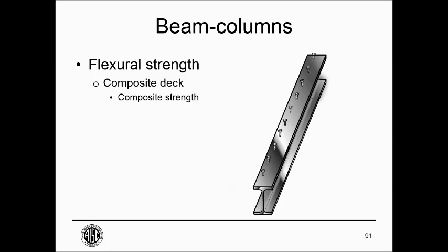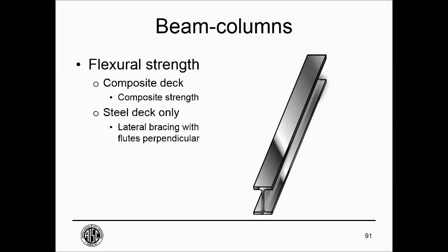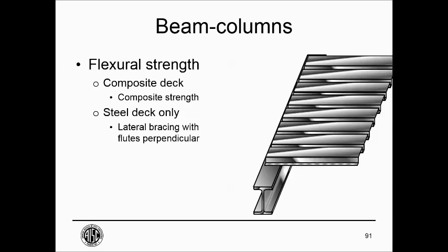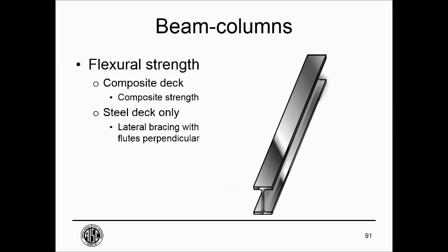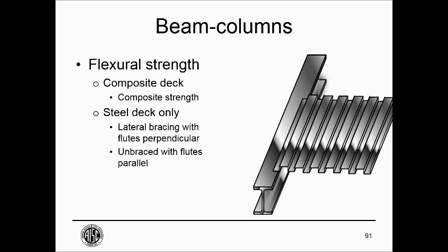For flexural strength, we could have a composite deck, so we use the composite strength in that case. We could have a steel deck that could brace us, or we could have a steel deck with flutes parallel, and a lot of engineers just consider that unbraced between lateral brace points.